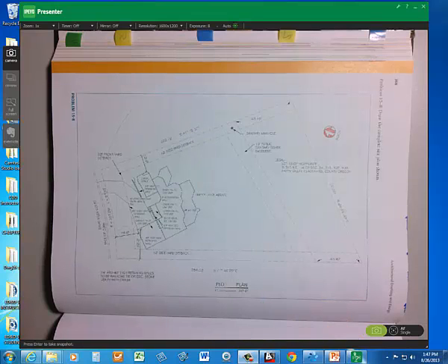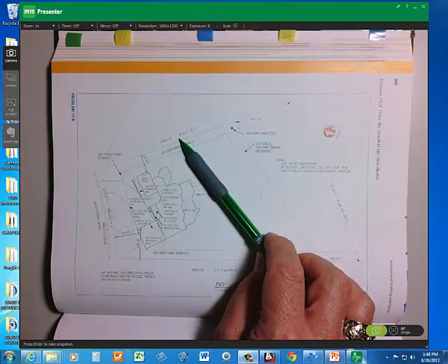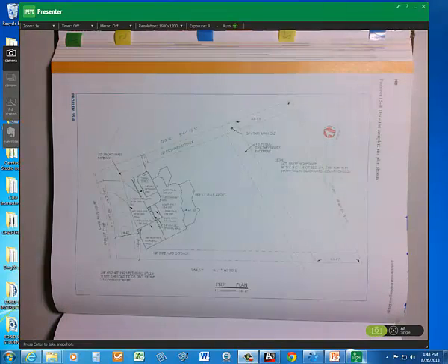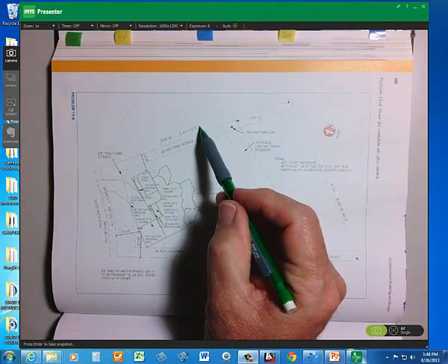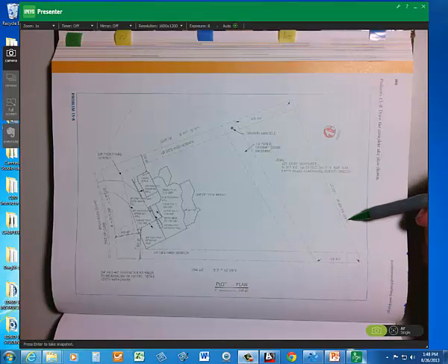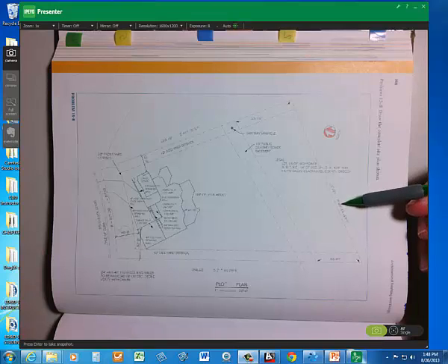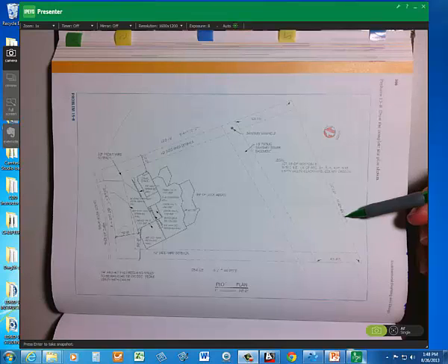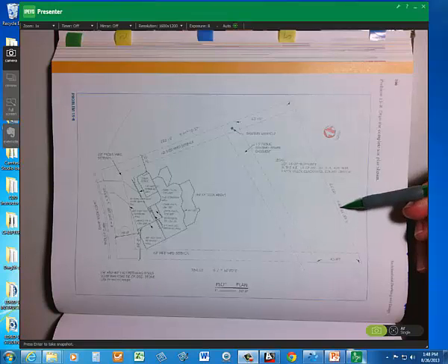When you're entering that, you will use the surveyor's units. So you will enter south. Well, that's not a good example because you're going to have to figure out what bearing this is. So we'll use this one over here. South 43 degrees, 33 minutes, 49 seconds west. So when you enter that into AutoCAD, you'll enter S 43D, that's lowercase d, 33 apostrophe, 49 quote mark, W.